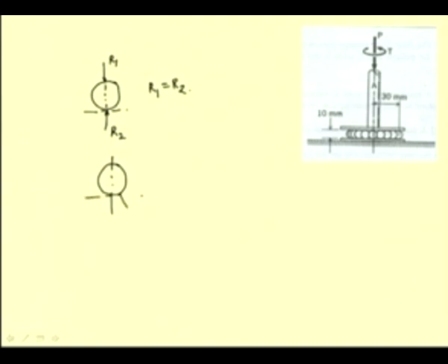So, this reaction shifts to a point, the distance to which it moves is equal to the rolling resistance, that is 0.0127 mm in this case. So, the force coming from the top face, which is R1, is also displaced by a distance of 0.0127 mm. The radius of this ball bearing is 5 mm.